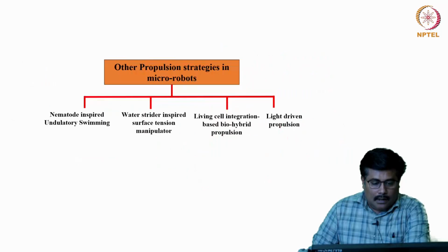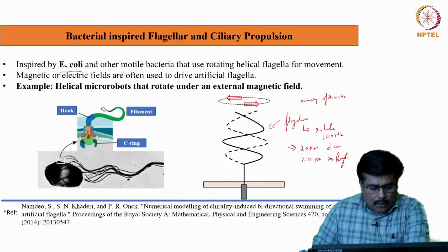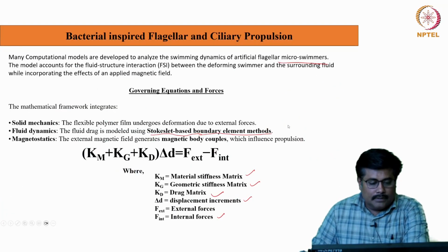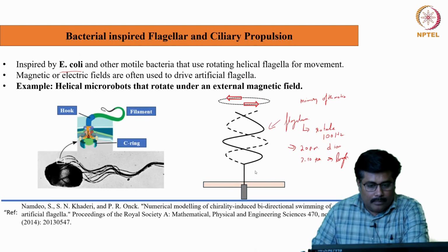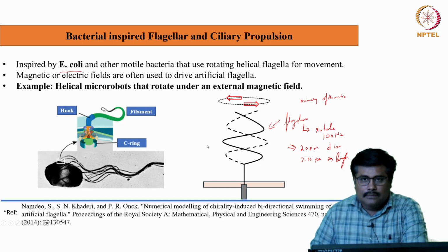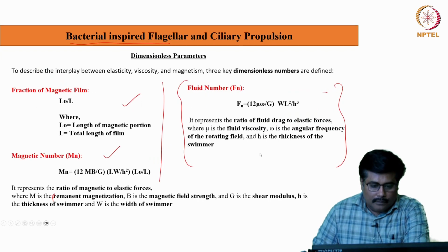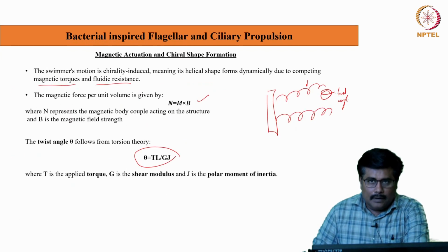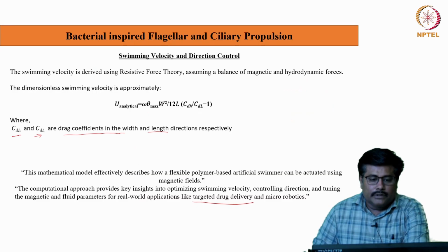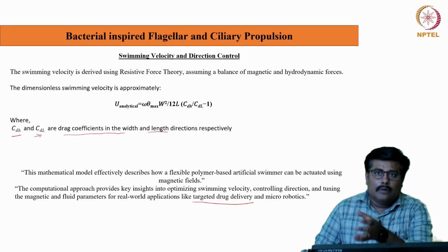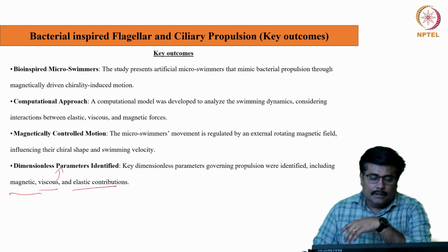And then we have discussed some of the key parameters involved with bacterial inspired flagellum propulsion. In fact, we have discussed in detail the different configurations involved in these bacterial inspired flagella, the different dimensional parameters involved, the magnetic actuations, the overall swimming velocity, and the directional controls.